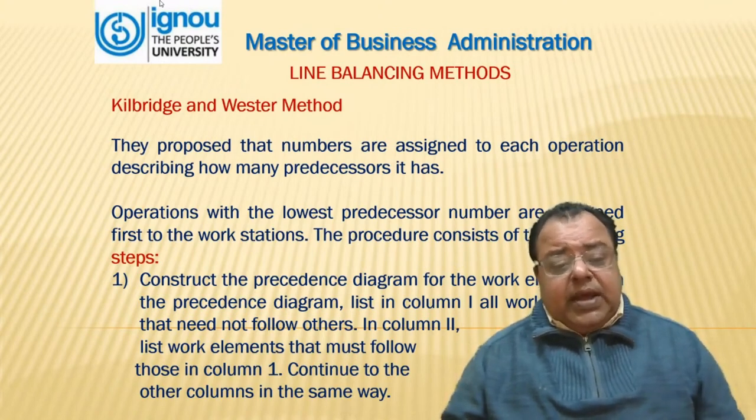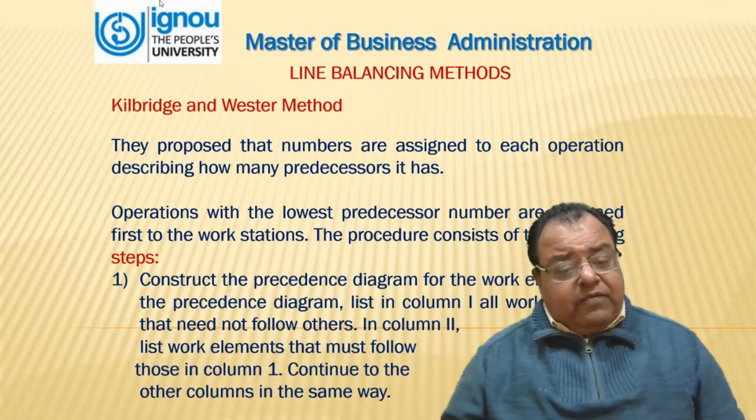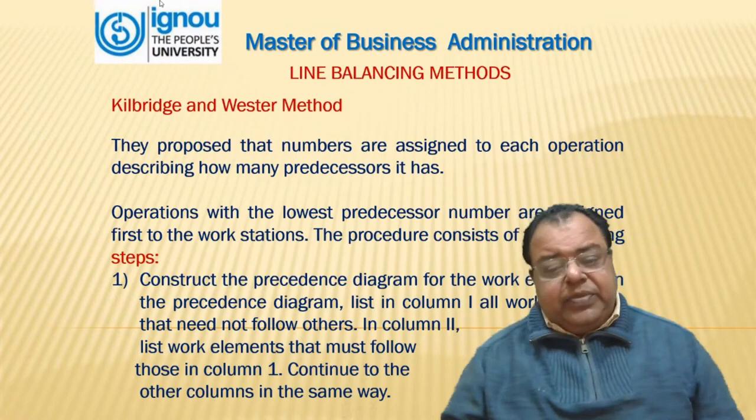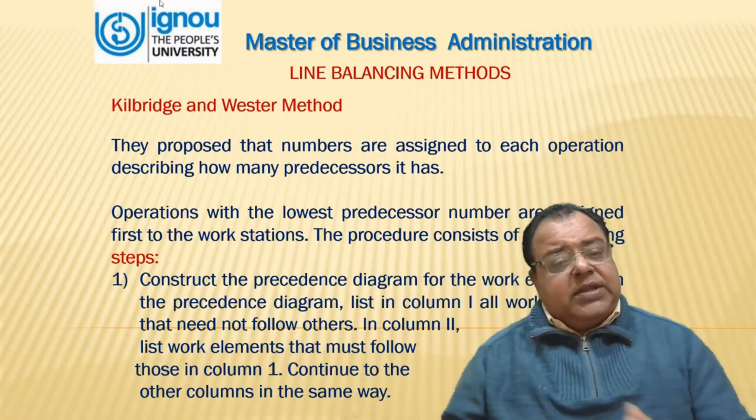Number one, construct the precedence diagram for the work elements. In the precedence diagram, list in column 1 all work elements that need not follow others. Column 2, list work elements that must follow those in column 1. Continue to other columns in such a way.